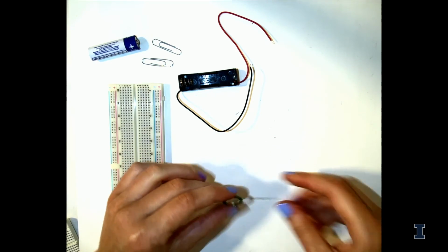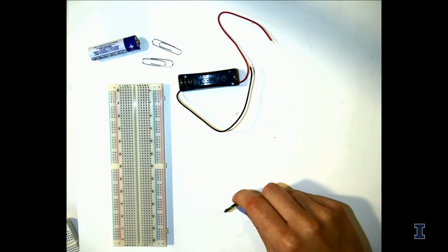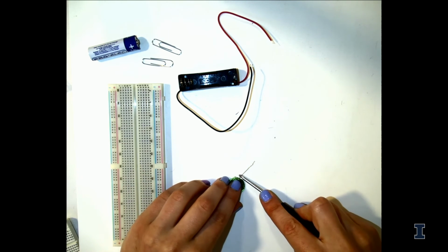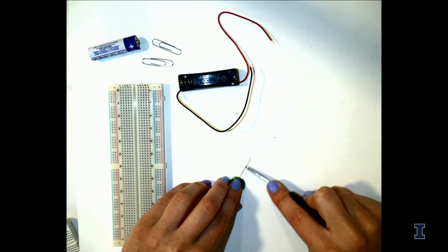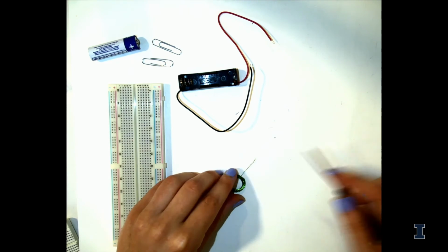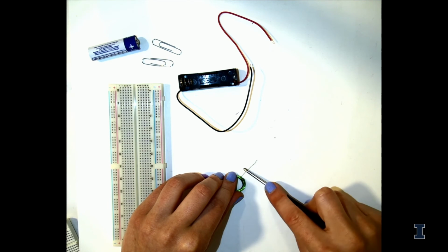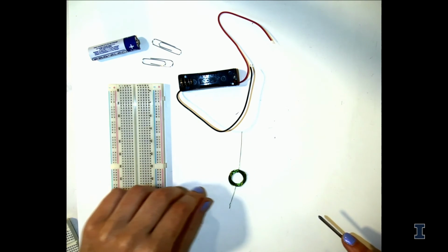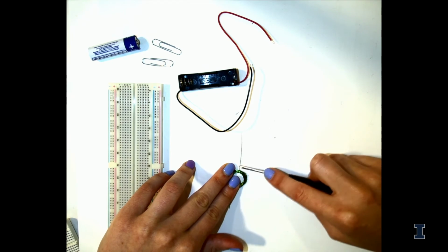All right. So after you have a nice tight loop that's self-supporting, pretty snug, you want to take a scissors or a wire stripper, and just using the edge of the scissors, which I'll just use a screwdriver right now, you're going to run the sharp end against one side removing the green insulation. So you'll notice that you can start to see the copper. So it's going to turn brown on this side. Then you're going to turn your loop around once that's done. And you're going to remove all of the insulation.